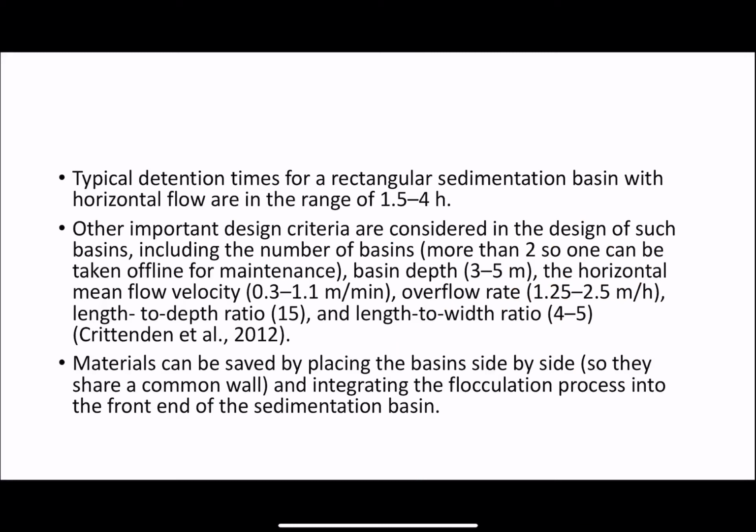Typical detention times for a rectangular sedimentation basin. Remember, what's detention time? The time it will take the water to stay inside the sedimentation tank. With a horizontal flow, of course, no vertical flow here, it is 1.5 to 4 hours. This is the design detention time.